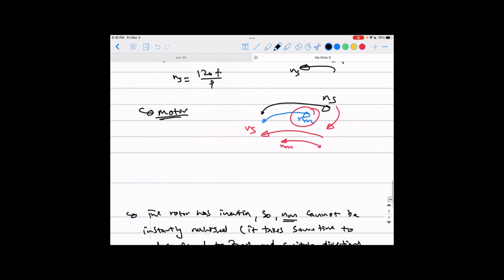If the motor is just rotating clockwise and you want to make it rotate anti-clockwise, you just switch off the supply and change connection of any two phases, and the motor will start rotating again, but in the different direction. The whole point is, what if you do this while the motor is online? The motor is now rotating into some way and you just instantly switch two phases. And now the motor is required to reverse direction instantly, but it will not do this. It will be very hard braked, okay?